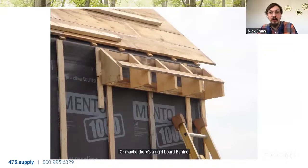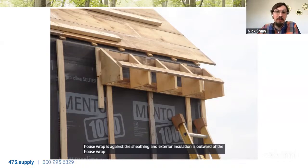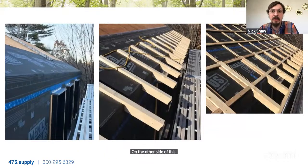But I would say typically that house wrap is against the sheathing and exterior insulation is outboard of the house wrap. So I think this is probably dense packed cellulose or mineral wool, batt or unfaced fiberglass batt on the other side of this for all these assemblies here.